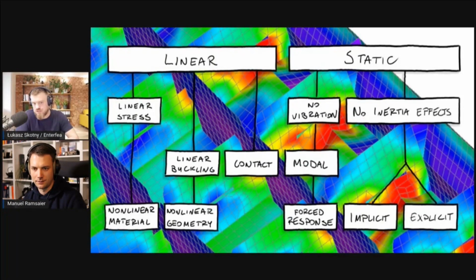Yeah. The reduction factor due to buckling can easily be like 0.3, 0.4 in a reasonably designed beam element. Structural steel, I mean. Yeah. But still, this is perfectly usable. You can analyze a very big steel building using linear buckling. Nobody would say that that's a stupid idea.